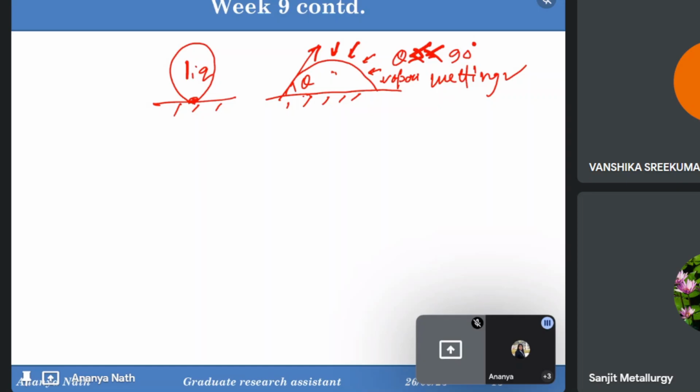As I already said, silicon absorbs on the SiC interface and improves the wetting of the SiC by forming a strong chemical bond with SiC. So it's all about the wetting of the SiC, because one thing we have learned is the processing by which we can process, but this wetting is more important than processing, because anyhow after making the metal matrix composite you can get the near net shape by turning or some machining.